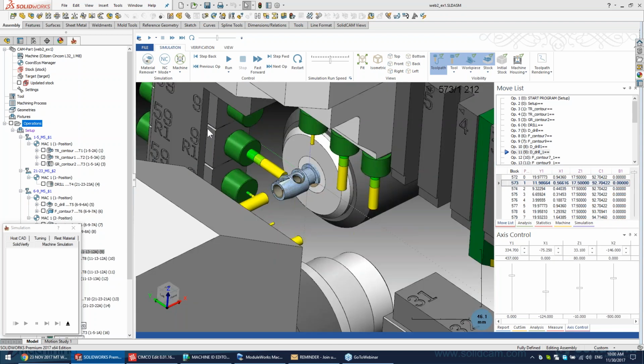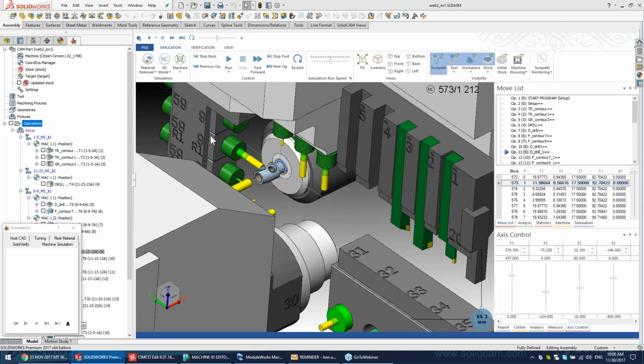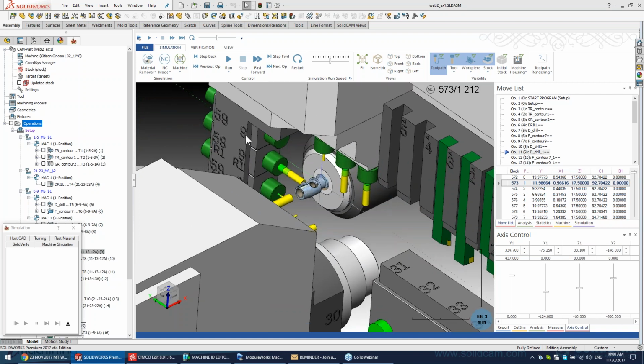with tools on this device, which can be mounted by the operator cross or axial, perpendicular to Z or parallel to Z. It's fixed by bolts. There are machines with this device on a B-axis, a simultaneous B-axis. Here, this device is not controlled by an axis, it is fixed by bolts.